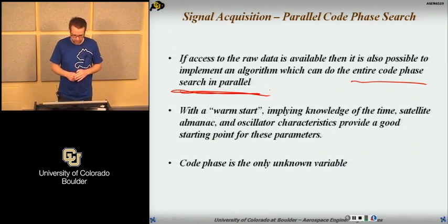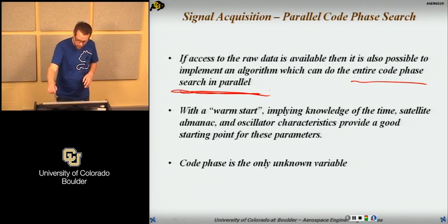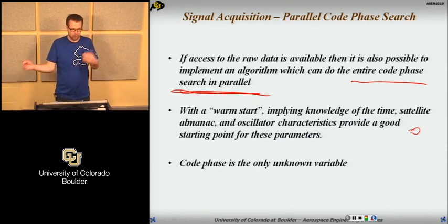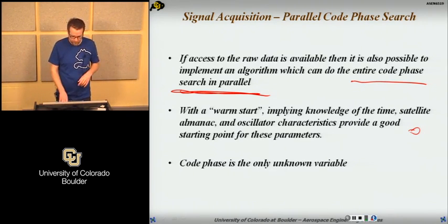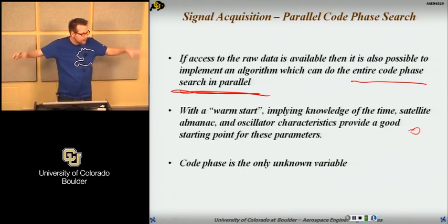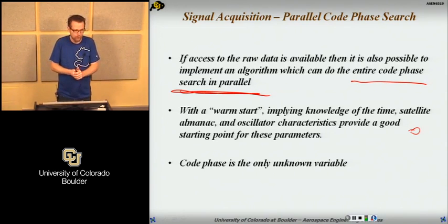If we know where we are, we can figure out the carrier frequencies, so we only need to test one frequency bin. Typically in this class we never know. It's too messy to implement all that to figure out where the satellites are at, but I want you to know that this is how you do it in a commercial receiver.